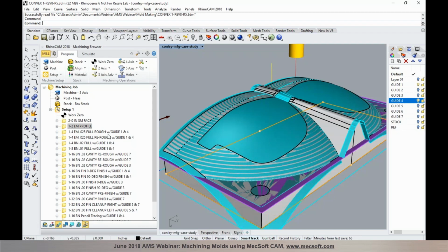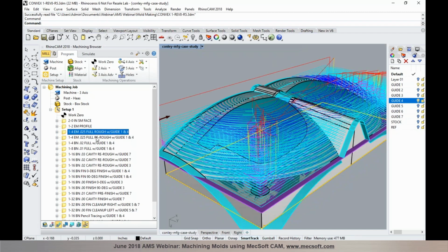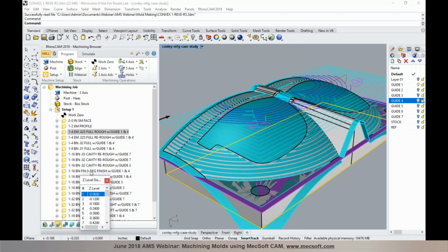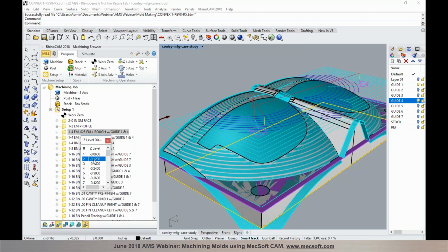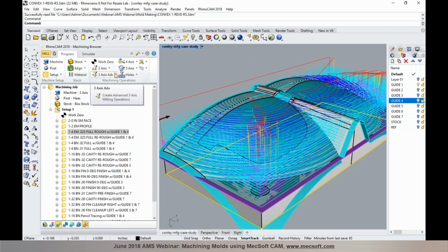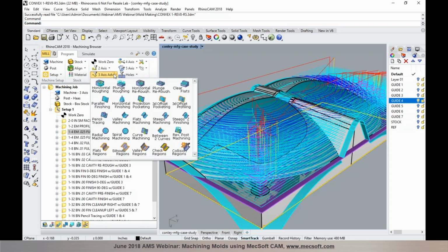So we have a 3-axis horizontal roughing operation programmed. This is known as horizontal roughing, or also known as roughing in levels. As you can see, we're doing roughing in levels or layers, called Z-level roughing, or also known as horizontal roughing. You can find the horizontal roughing under the 3-axis methods. It is available right from our Express configuration. You have 3-axis horizontal roughing.